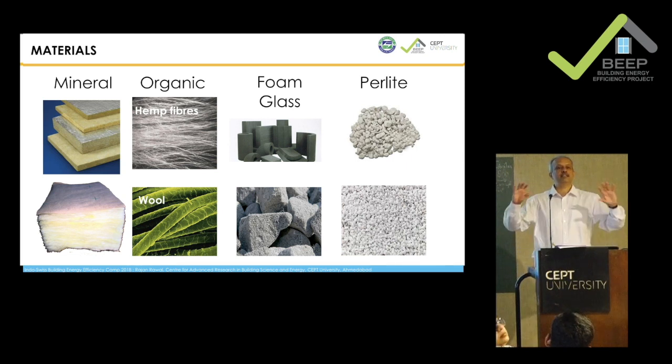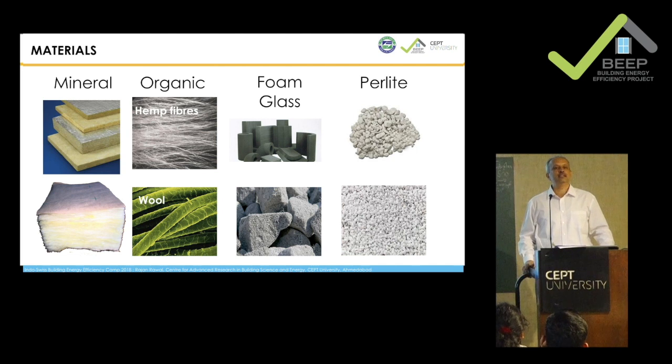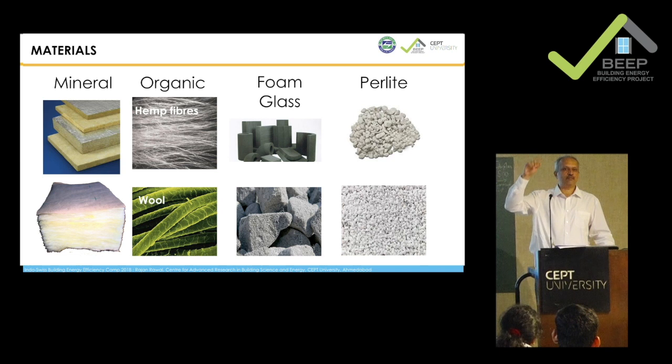Okay, so wherever there is external heat transfer taking place, first of all, you will identify those elements and you will place insulation. Now, place inside or outside, that's a second question. They are roof and walls. Floor? Is it external? Ground floor. Okay, fair. So we will have something on the floor, we have a wall, and we'll have roof. Now let's talk about where will you put it.